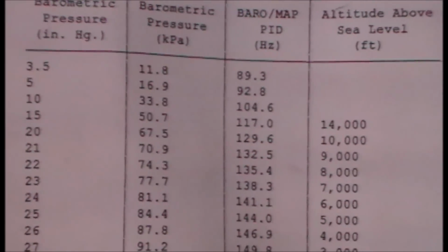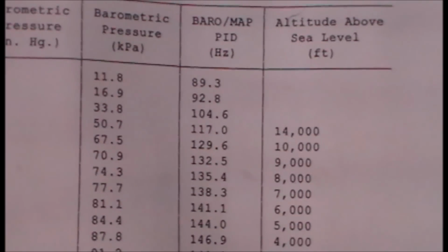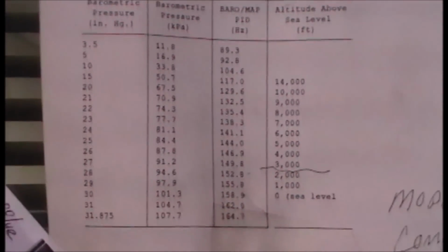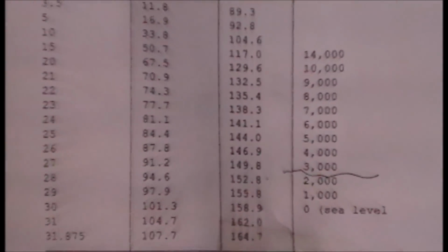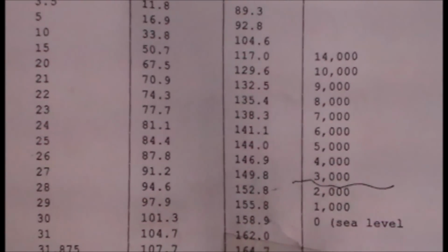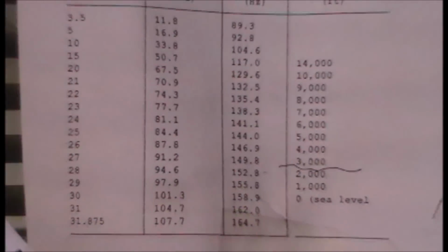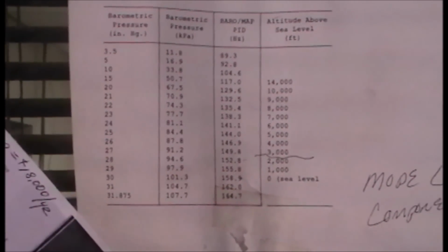At 129, wherever I had on the scanner, it shows me at 10,000 feet. So the computer's not going to even try to give me enough fuel, because at 10,000 feet there's not enough oxygen to burn it. So that's where my issue lies. We'll go from there.